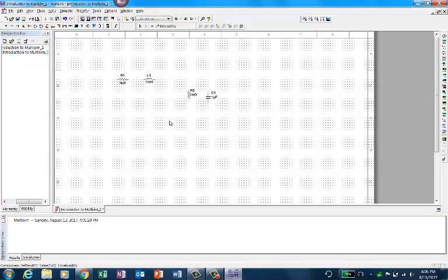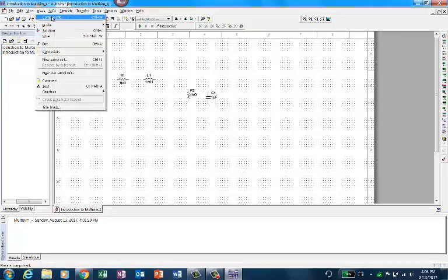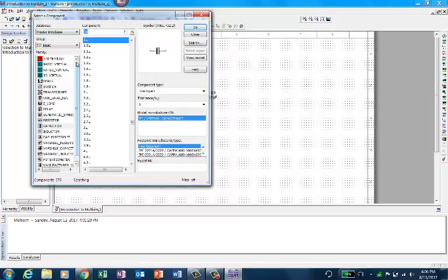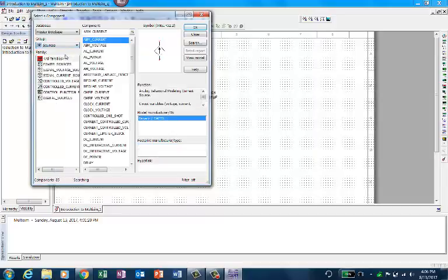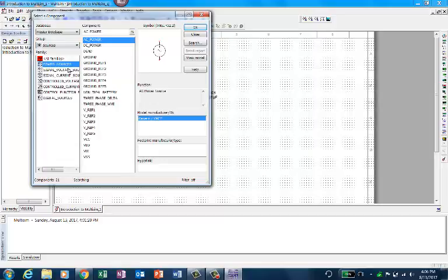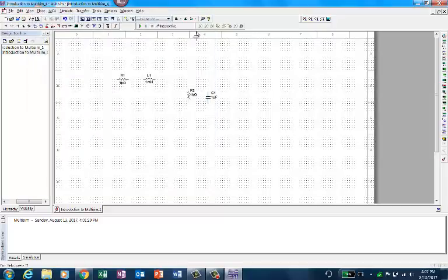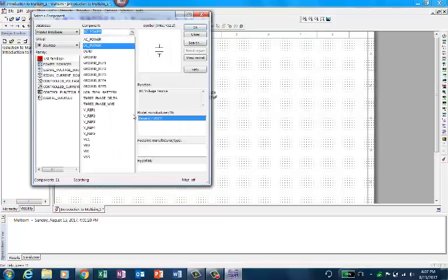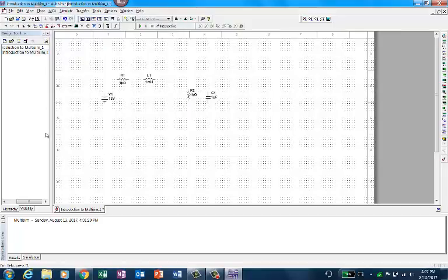Let us also get a DC supply. Say we want to put a DC supply, so we need to go to the families. What is the basic one we are looking for? Sources. Once you go to sources, we choose what sort of power source we want. We want to put a DC power. We can put a DC power or AC power, and we put this DC power. We have now a battery. Once you have a battery, we have done that one now.